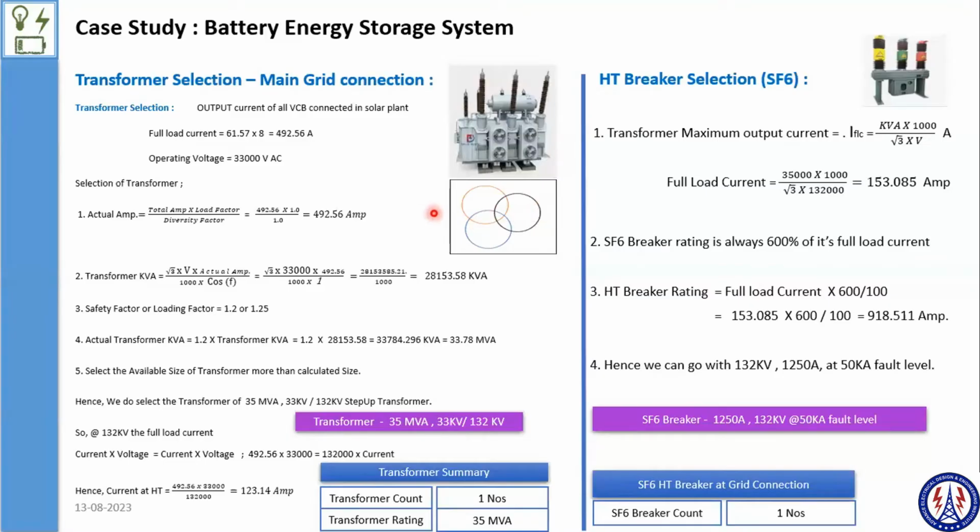This is the provision, this is the system we are preparing. And how the operation is going to happen, we will see. I'll explain with the diagram. Now this is the system. Let's say the system must be capable for the worst scenario. You have the solar plant of 32 megawatt. You have the final transformer capacity of 35 MVA, correct? Even if, let's say, some incident occurs, your battery plant won't work, and for some time you need to push every power to the grid. What will you do then? At least the plant should run. That would be the target.